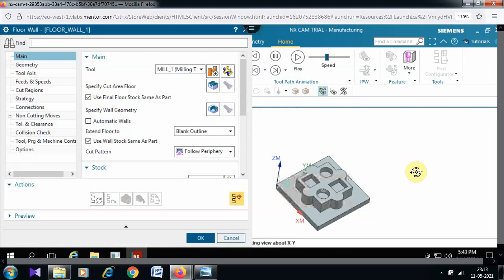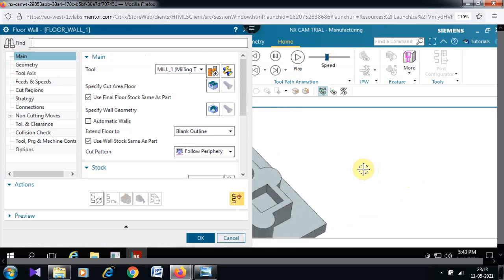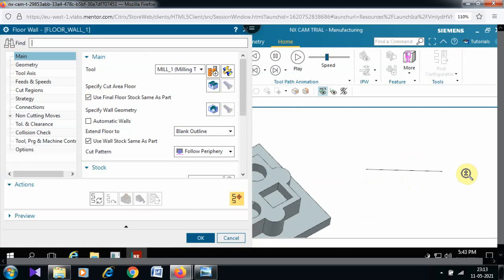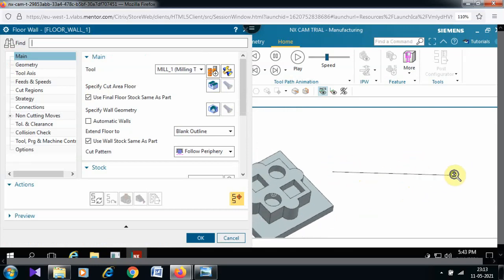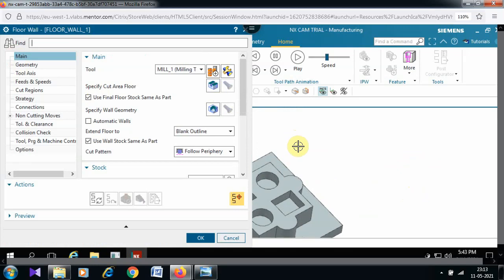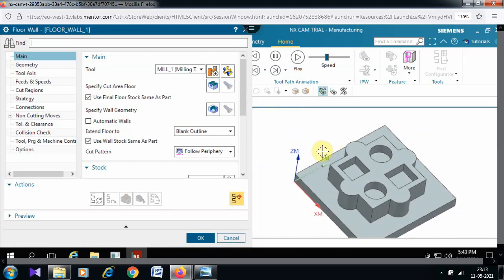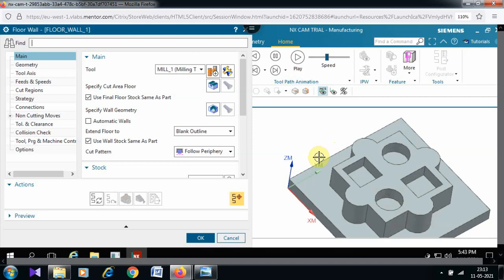So for this we need to have this profile a little bit like this. Zoom it up. We will pan this also a little bit if possible. Okay, shift middle click will pan, and your scroll button, middle click scroll, will actually zoom in and zoom out.